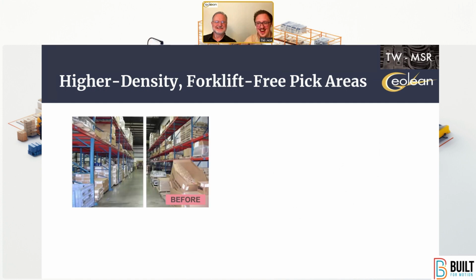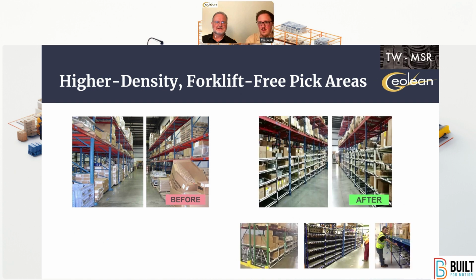Sure. This is a before and after of a lane that got about 170 more pick faces. Exactly. And this is a great example of the issues we talked about in the warehouse, and these are solutions that we've addressed with those issues. FIFO is a big one here, right? When you're picking parts off a pallet, there needs to be operator discipline to grab the right part. When you've got a flow rack in place, you're going to pick from the front and load from the back.